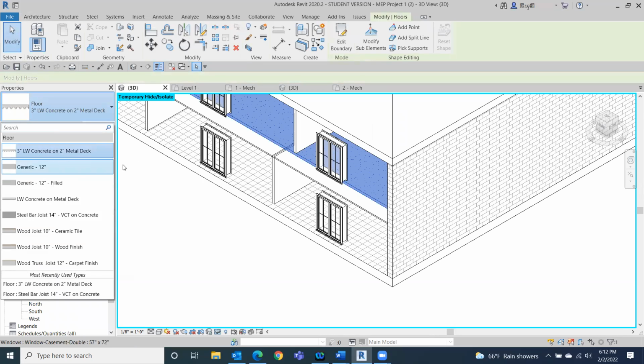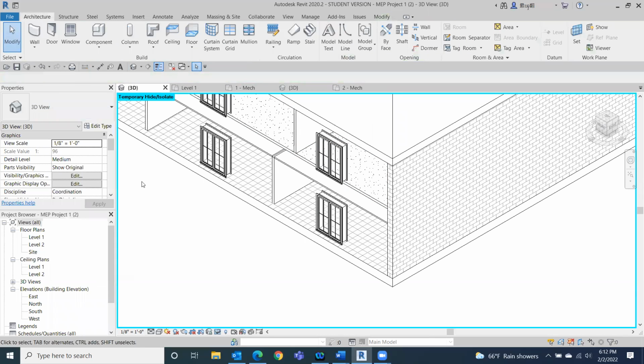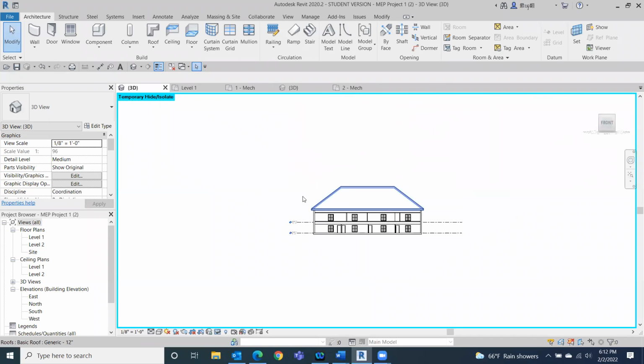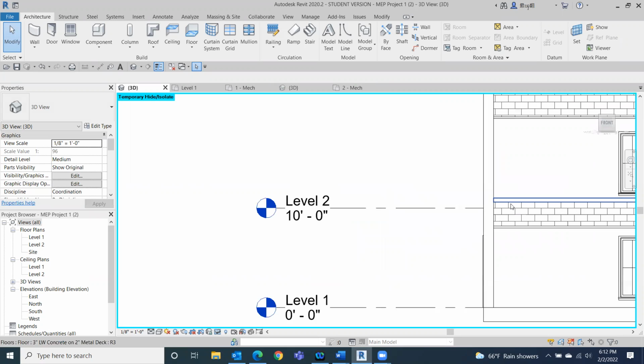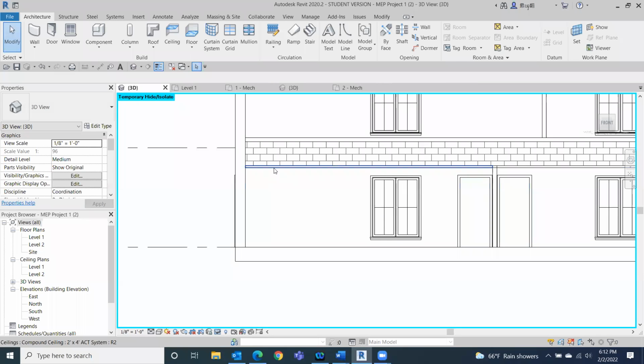But aren't we going to want to have like a drop ceiling so we can put the plenum in there and all that? Correct. That's why I want you to change that to 3 inches at that point. And then we're going to have an 8-foot ceiling right there. Okay. This space between here and here is going to be our plenum that we're going to work with. So if you kept that at 12 inches, that would cut out so much workable space right here.